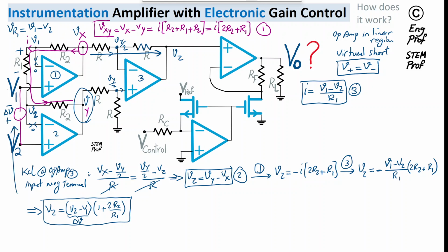that if we have a sensor in this instrumentation amplifier, and usually that's the case in an instrumentation amplifier, the delta V across the sensor is pretty small, on the order of, let's say, hundreds or tens of microvolts. And therefore, even with the amplified version here, the Vz, the voltage sensed at the positive input terminal of op-amp number 4, will be pretty small, depending on what we set for R2 and R1, on the order of tens of millivolts or 100 millivolts, or in that range.